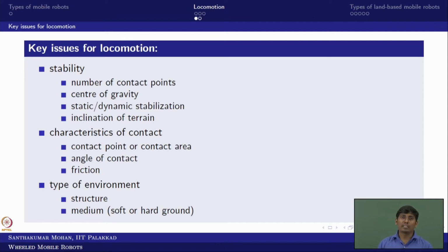Now this understanding may vary when the terrain is inclined or bumpy. So then, you have to understand whether the stability is ensured or not. For example, now you have a ramp of probably a 20-degree ramp. Based on your contact and friction, if your friction is sufficient to hold on the 20-degree ramp, then you are safe. So that's why stability is one of the critical points.